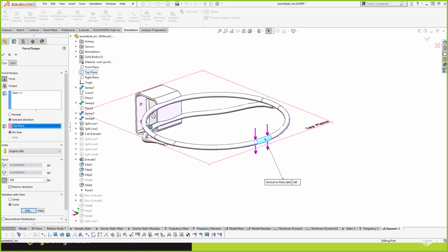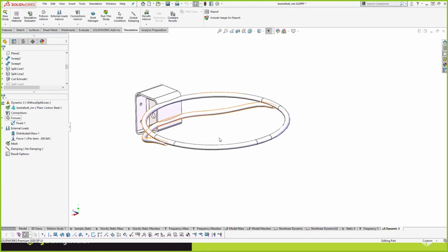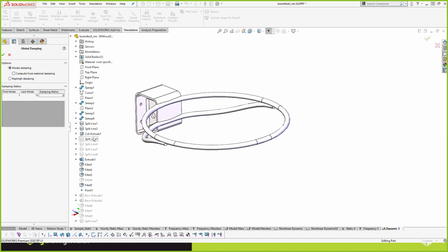Alright, so I'll apply that force along with the mass itself of it. And in addition to this, I'll add some damping. If I edit this damping, I'll say that this thing loses energy at about a rate of, in the ballpark of 2%. It's not precise for me to call this a percentage per se, but for very low damping values, it behaves very much like a percentage. So it's sort of like it's going to lose 2% per oscillation.